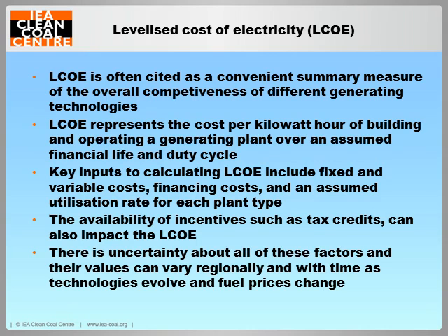is that the trade-off between capital and operating costs of different technologies makes comparing the overall costs of different power plants somewhat difficult. The levelized cost of electricity represents the per kilowatt hour cost of building and operating a generating plant over an assumed financial life and duty cycle. Key inputs to calculating the levelized cost of electricity include both fixed and variable costs, financing costs, and an assumed utilization rate for each plant type. The importance of the factors varies among the technologies.